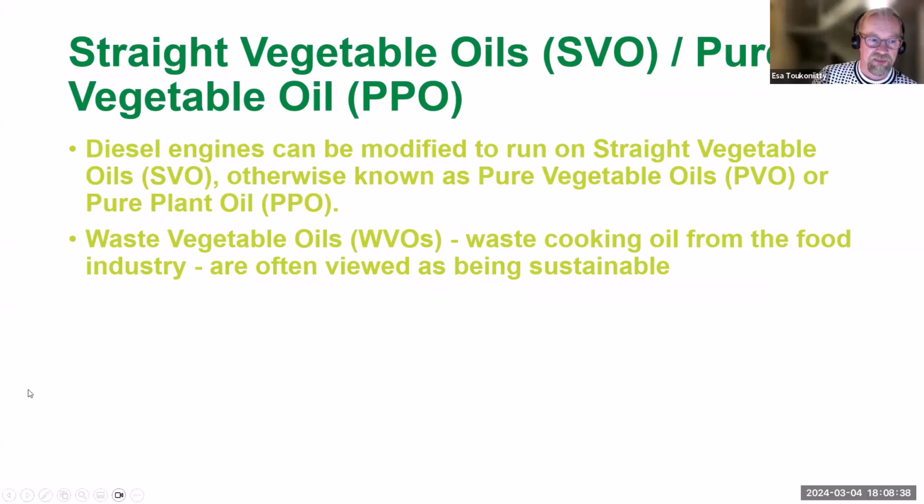And this was a good reminder to me. I already mentioned this last time to you: straight vegetable oils, or pure vegetable oils. So in principle, these simpler diesel engines, particularly the older ones, were originally designed so that they'll run with the regular vegetable oils. So this can be used as fuels.